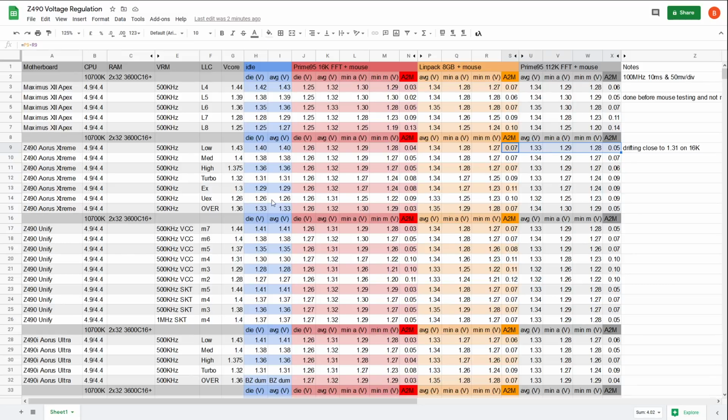But yeah, override mode is pretty cool. I'd highly recommend that you at least try it out. If you adjust the LLC settings, you're literally just going to end up raising the voltage. Override mode, from talking to Gigabyte, is designed to work with auto LLC. You can still change the LLC, because the way LLC is implemented, you're telling the voltage controller to change LLC levels, and override mode is telling the voltage controller to change voltage levels. So you can technically run override mode with ultra extreme LLC. It's just that override mode isn't capable of smoothing that over.